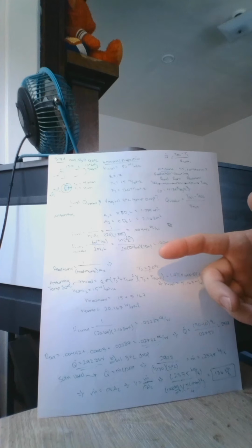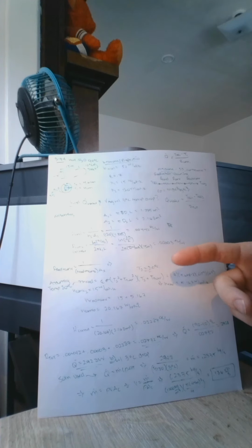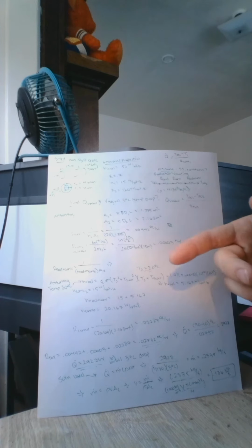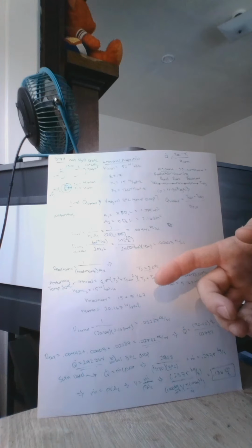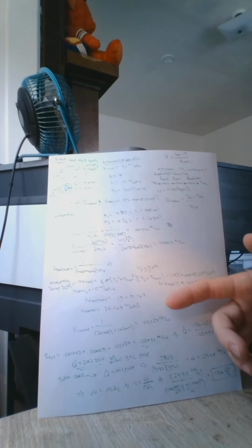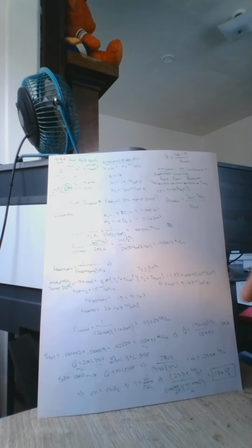We also had to calculate the radiation heat transfer coefficient to calculate the radiation resistance, as well as some convection going on from the fluid motion inside of the pipe. We then used our h's and all of our R's to get an R total, which could then be solved for a Q.